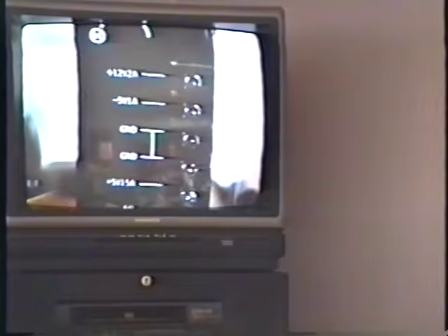When you look at the power supply, you have 2 screws down here that are labeled AC. This is obviously where the AC power comes in, the AC power that powers the power supply, 117 volts AC, 120 volts AC, whatever you want to call it. The next pin up is called frame ground. It says FG, frame ground is what that really means. This is AC power, frame ground. Not field ground, although some people call it that. It's actually frame ground.